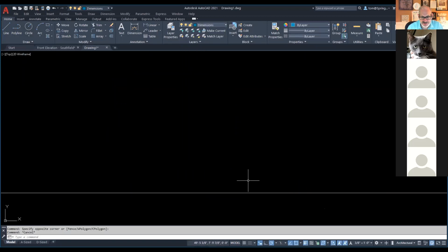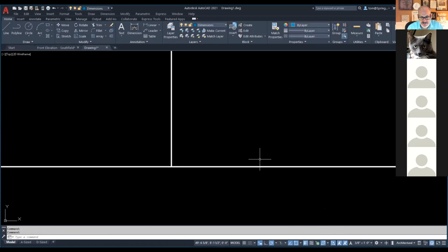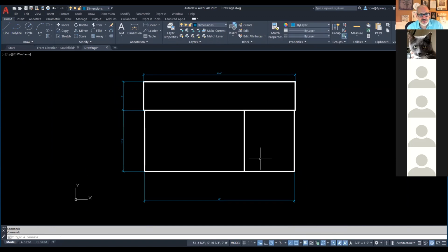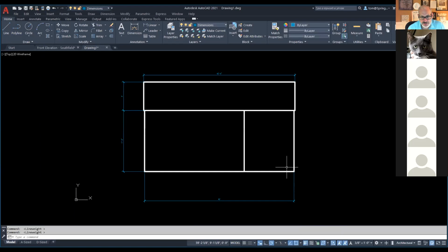And we'll zoom into that right there, because I am not seeing my line weight. Okay, it's not showing up. Let me change my line weight settings, and let me turn it up. There we go. Now I can see that. Now I got my line weight turned on, and I can see a nice projected line. So that's nice and fat. Your line weight allows you to turn that on and off, thin lines, thick lines. Just something you can work with. Okay, so I've got the basics.